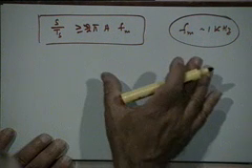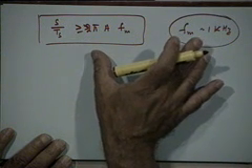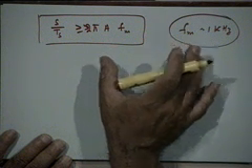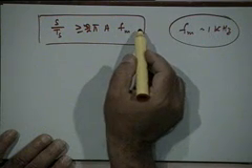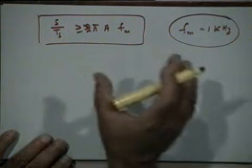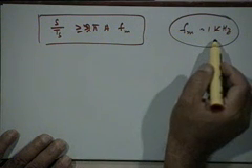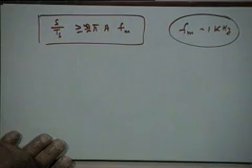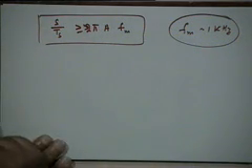Alright, the point that I was making was that for voice signals we try to satisfy this condition at some fixed frequency within the voice band, which is typically 1 kilohertz. This is just a remark I am making from the design point of view. It is not important from the theory point of view. Okay, this is one problem with the delta modulator, the slope overload situation.